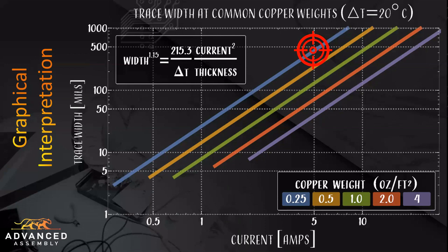By using the same method and equation, this would go down to a 130 mil wide 1 ounce trace, and then you could use a 40 mil wide 4 ounce copper trace. So remember that this assumes unobstructed convection of surface traces at a standard temperature and atmospheric pressure. These equations are going to need to be reviewed if you are using space and downhole product applications.